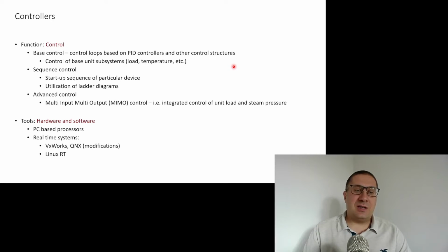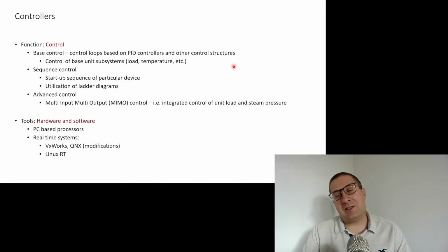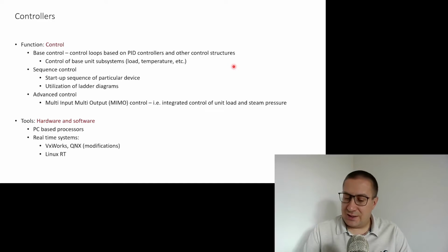But also we can implement sequence control in such a controller. So we can implement startup sequence of particular devices or the whole units. For this purpose, we can use the ladder diagram, or we can use other dedicated algorithms and programming functions.